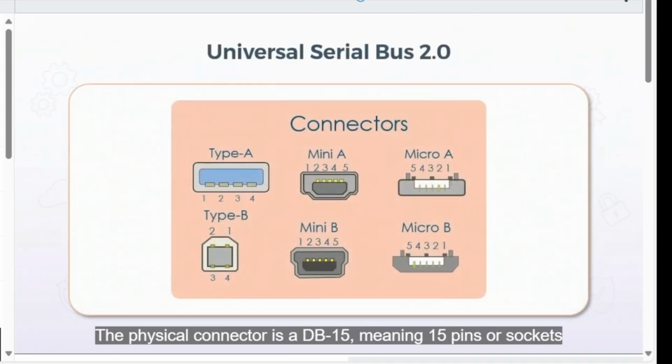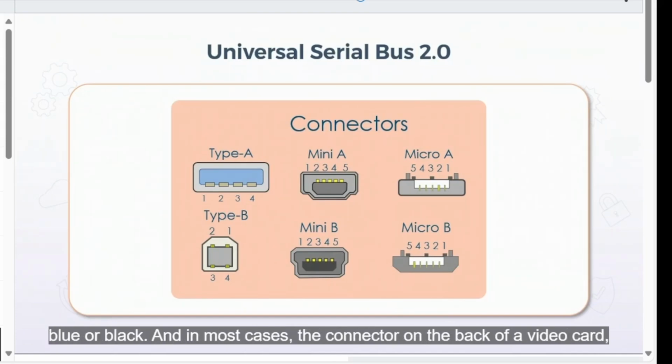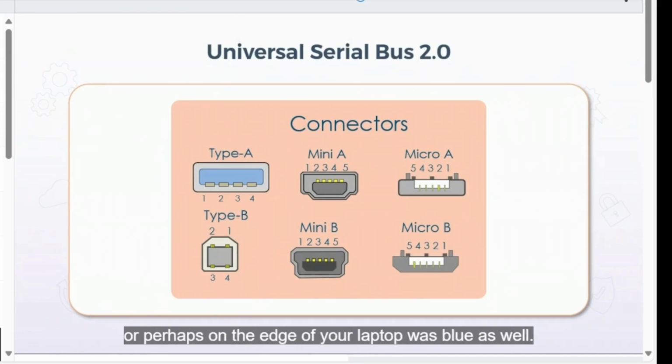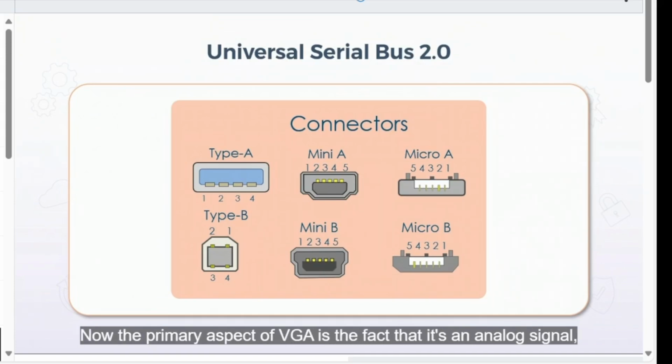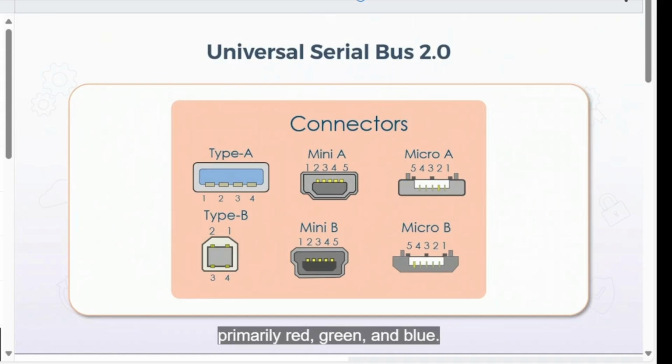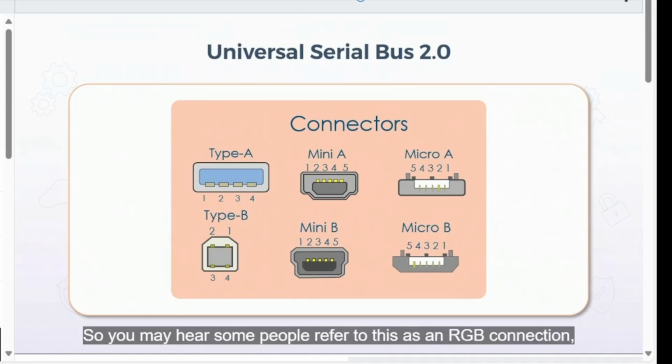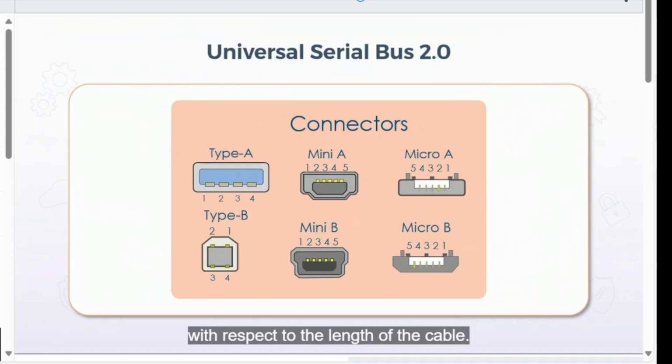As for the connectors and cable specifications, that first comes down to the version of USB, and while there is a version 1, in terms of what you are likely to encounter these days, we'll focus on version 2 and higher. So for starters, the Type A connector is probably what comes to mind for most people when they think of USB. It has 4 pins along one side only, so it can only be inserted in one orientation. The port on the computer was almost always, if not always, female, and the cable would have the male connector, but the Type A connector would be the most common type of connection at the end of the computer itself.